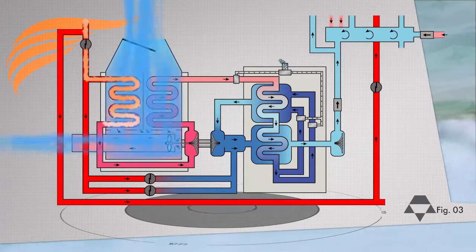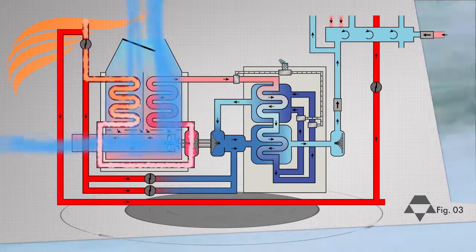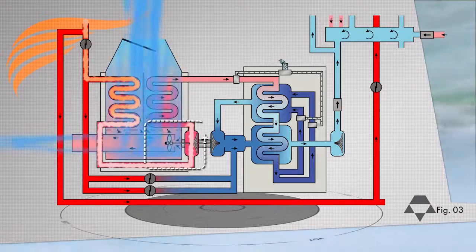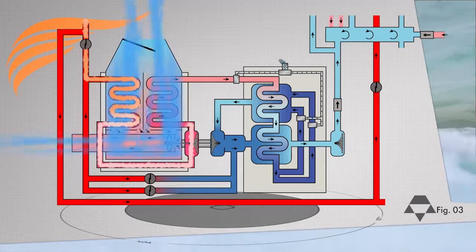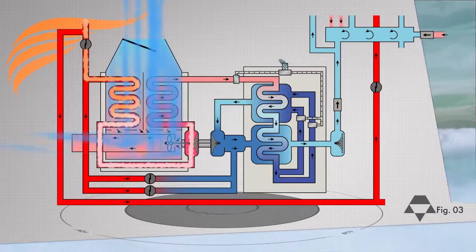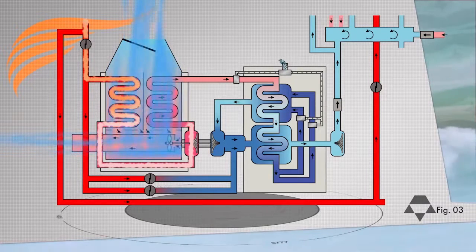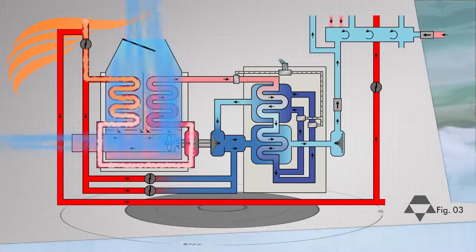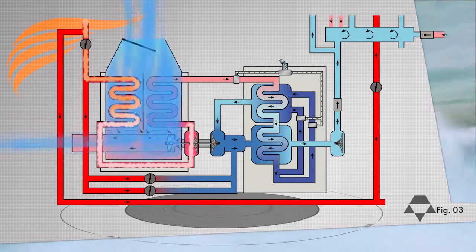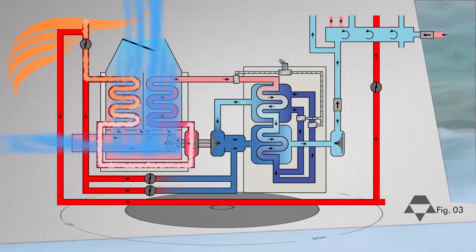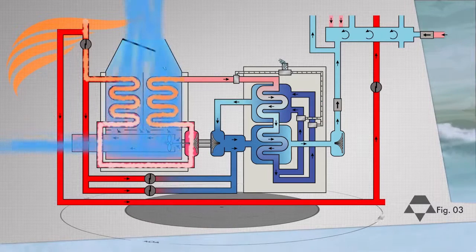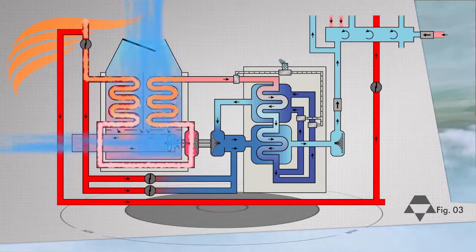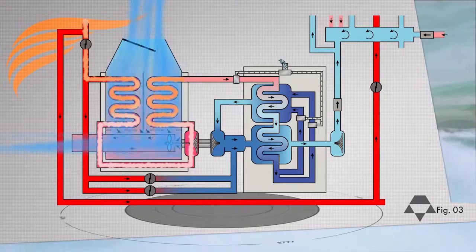After the first stage of heat exchange, air flows into the ACM compressor stage. The compressor stage compresses air from the primary heat exchanger to increase its pressure. In the process, heat is also produced. Therefore, the air's temperature increases once again. Because of this, and after air has passed through the ACM compressor, it passes through a secondary heat exchanger where again it's put into contact with ram air.